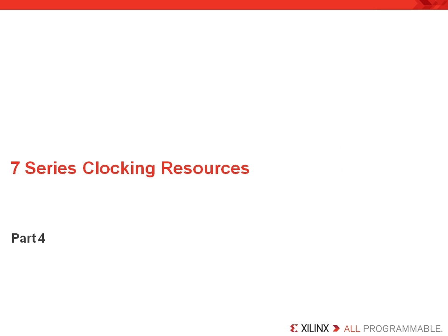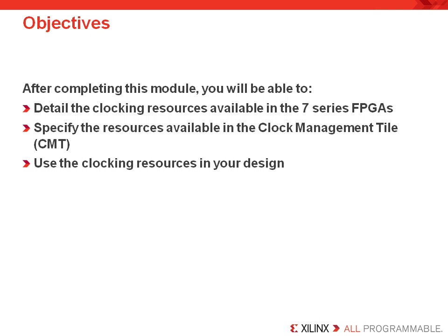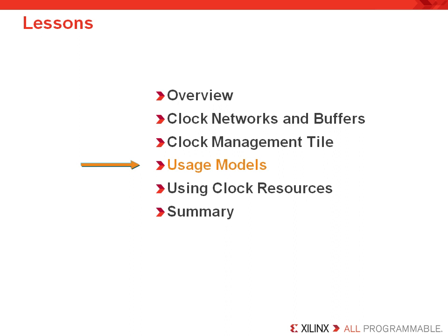Now the MMCM also provides a fixed phase shift, interpolated phase shift, and active phase shift functionality as well. This module wraps up our discussion of the clock generation capabilities in the 7 series products. Our objectives for this module are for you to understand how to take the knowledge we've given you regarding the clocking resources and the clock management tile and be able to add them into your design in some very practical use models. So let's get into usage models, and then we'll talk about how to use and get access to the clocking resources.